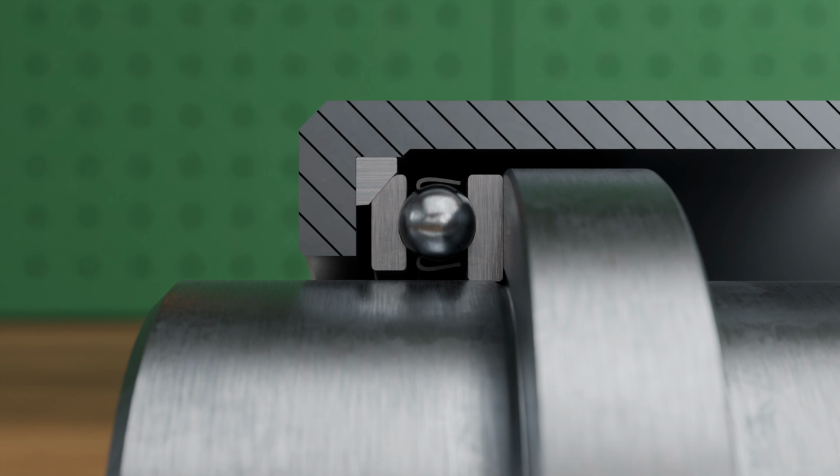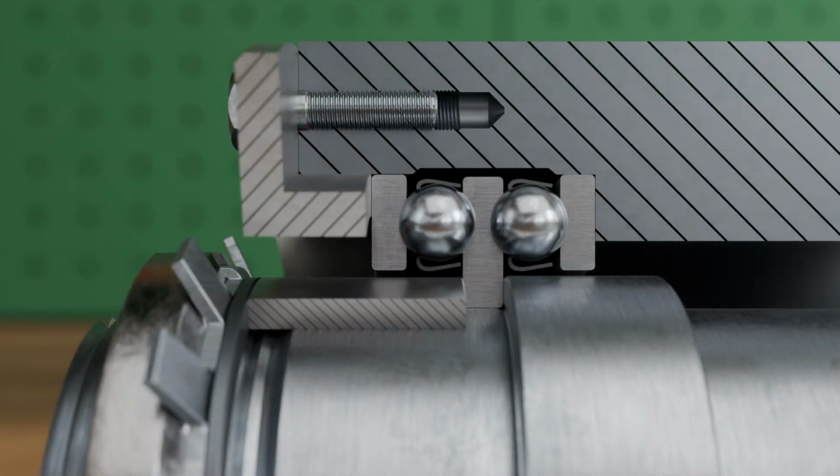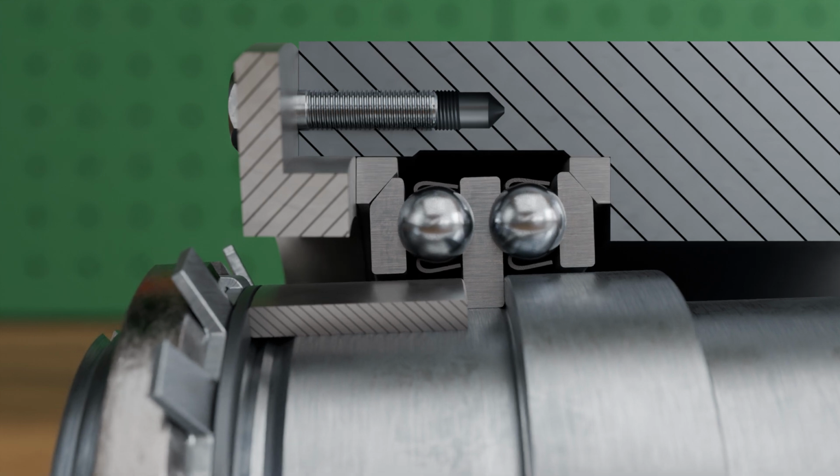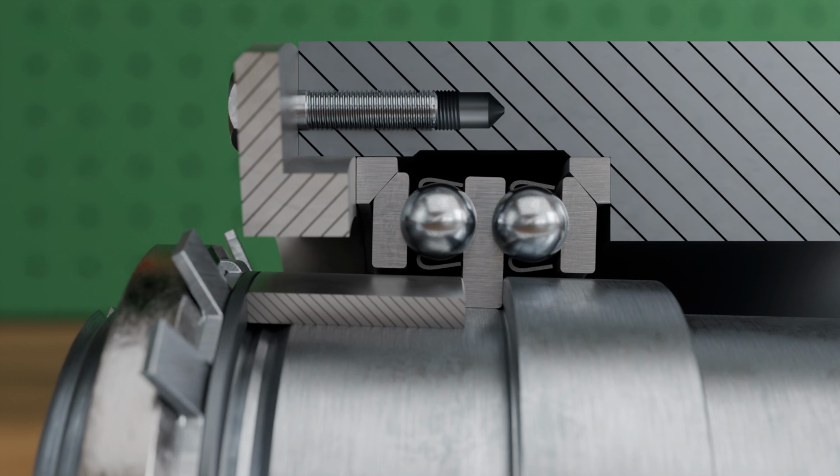For applications with axial loads in both directions, double-row variants are also available, where a set of balls acts on each side. The intermediate washer is connected to the shaft and functions as the shaft washer. It has a correspondingly smaller inner diameter than the 2 outer housing washers. These double-direction thrust ball bearings are also available with spherically shaped housing washers and matching seat washers to compensate for minor misalignments between shaft and housing.